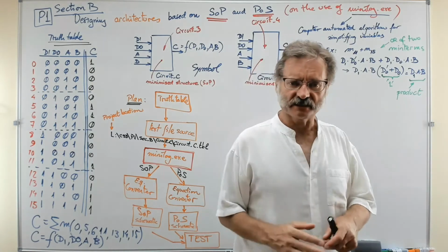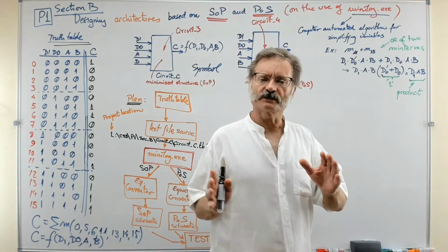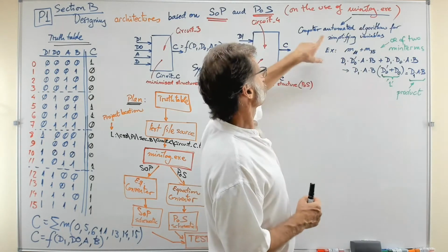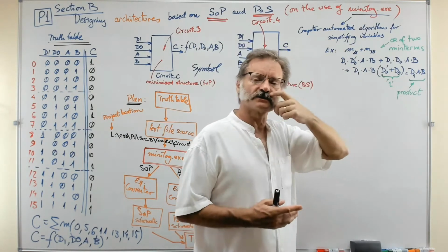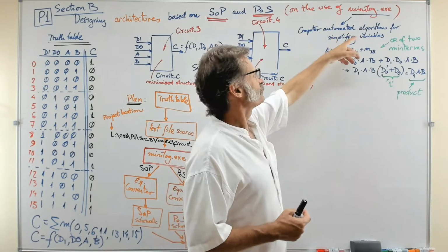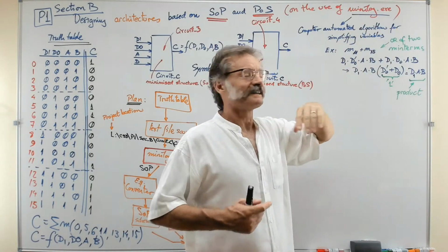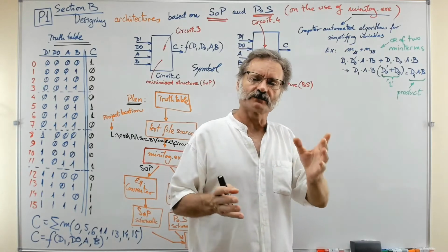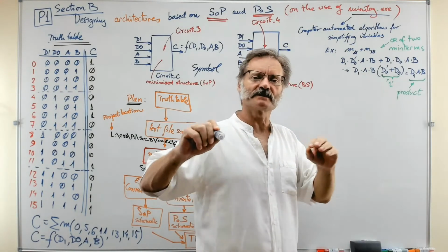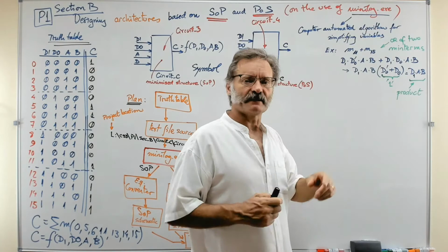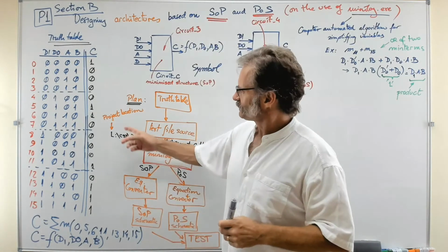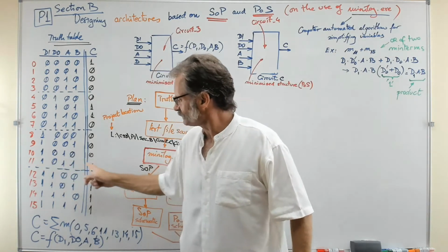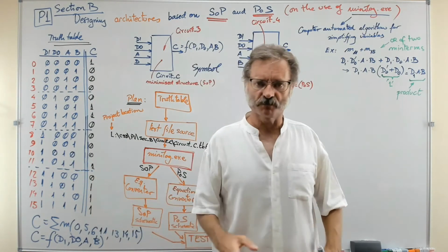So basically, what is this software going to do? Well, the software is going to automate, by means of a computer calculator, and using espresso algorithms, the idea of getting rid of variables when you can, using Boole's algebra, eliminating them. For example, take this situation. For example, let's take two minterms here. For example, the minterm 11 and the minterm 15, both.